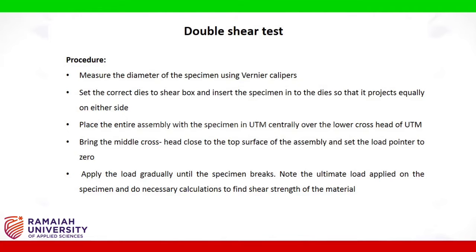Bring the middle crosshead close to the top surface of the assembly and set the load pointer to 0. Apply the load gradually until the specimen breaks. Note the ultimate load applied on the specimen and do the necessary calculations to find the shear strength of the material.